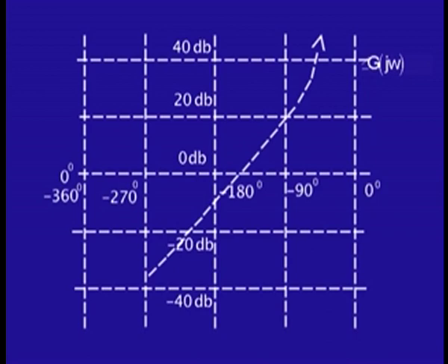This is not that. The z over 1 plus z transformation is still z over 1 plus z, but now one is looking at plotting it in a different way. And now you can ask a question similar to the question that we asked earlier for the gain and phase shift for the closed loop transfer function, where we had the polar plot. Now we have a plot which is no longer the polar plot, and therefore, since Nichols introduced this idea, it is sometimes called the Nichols plot.